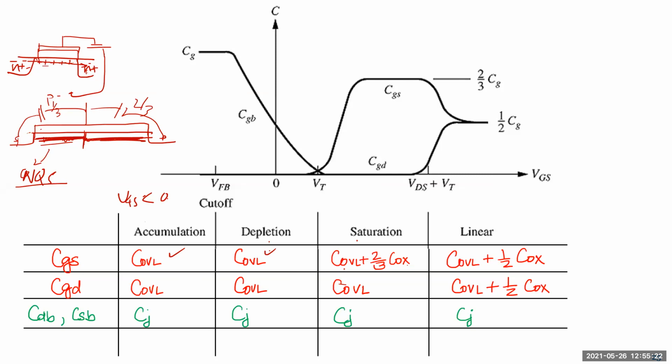Those are the issues at really high speed. But most of it will be captured by the model, the way they partition it, unless you are in the terahertz or hundreds of gigahertz range. Then you have to use the NQS model, which is very rarely provided by the foundry house.